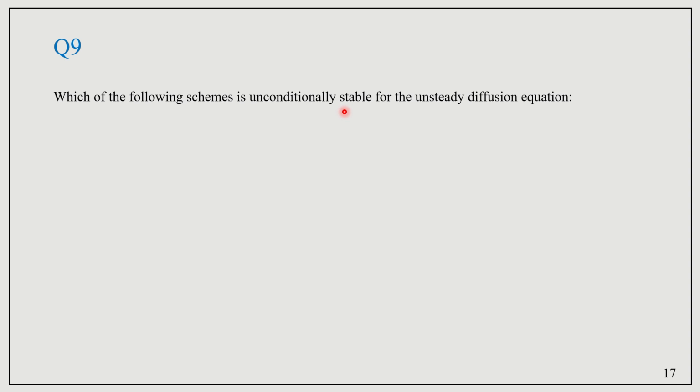That is, we need not fix the delta t. What the CFL criterion basically states is that we have velocity, we have delta t, we have delta x, and it should obey the CFL condition. So what it means is that we need to adjust delta t and delta x in such a way that the CFL condition is met. So we can say that we have a hold on parameters like delta t and delta x in order to get a stable solution.